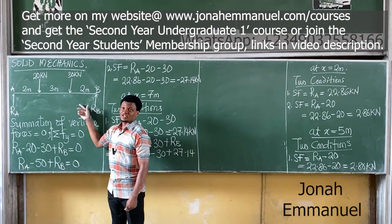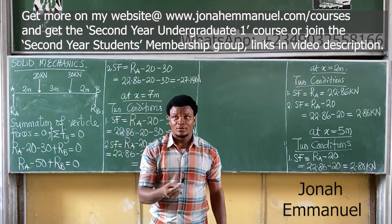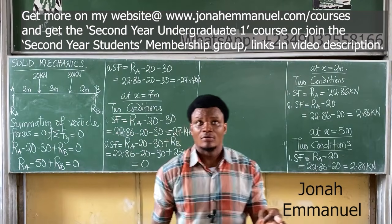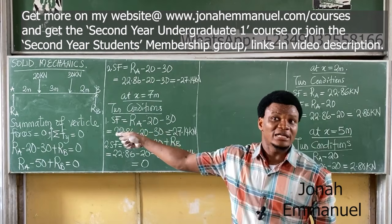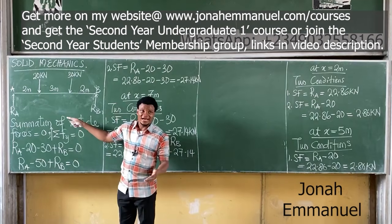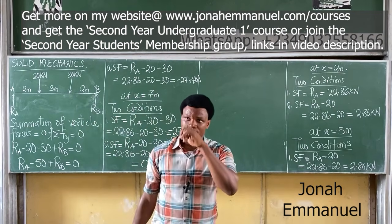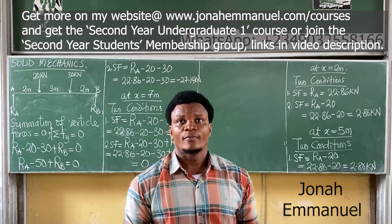So if shear force is equal to zero, that means this structure can actually work. That's it. Just a side note: if your shear force is not giving you zero at the end, most likely you're wrong. The real life implication means something is wrong with the diagram. If I set up this structure in a real sense, and I put a 20 kilonewton force and a 30 kilonewton force, the structure does what there? It will collapse. It's not working. But in an exam case, we'll say you're wrong.